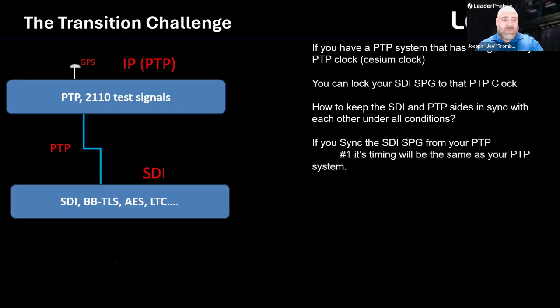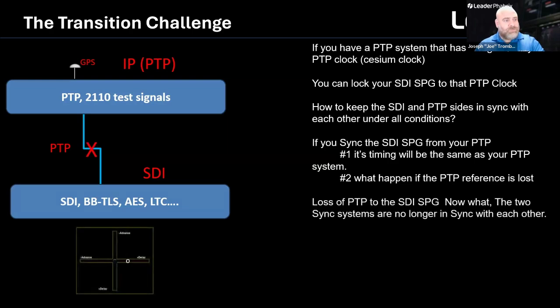So the main lesson is that picking one domain to feed to the other does not remove the design problem. It only changes which failure mode you have to engineer around. That's why it's recommended to design common source synchronization and a specified failover.